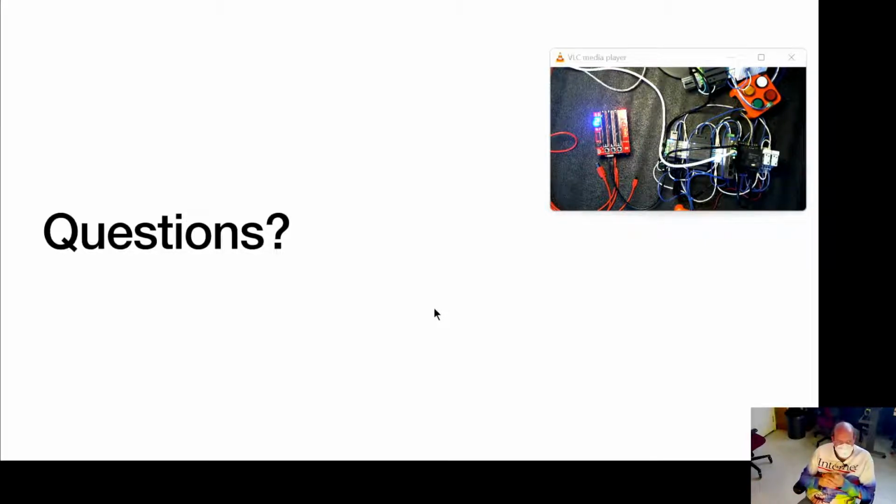The limitations they put on that is obviously you can't do motion from your virtual PLC. You can do virtual motion, but not like control a real servo drive or IOs or whatever. And the virtual engineering license can only have 4 hours of runtime before you need to reboot it, and then it'll run for another 4 hours, which for development and testing isn't really a problem. And that means that you can start. One of the reasons they and other vendors are pitching the simulation and virtual devices is so you can start developing your PLC code before your hardware and your control panel is even built.